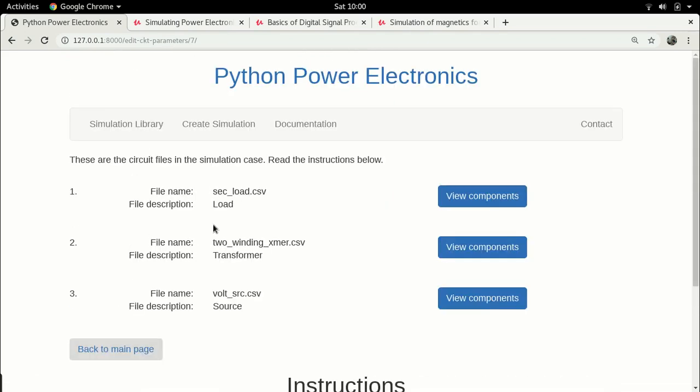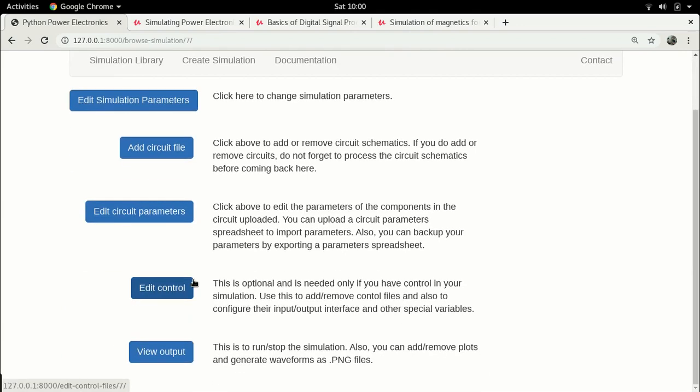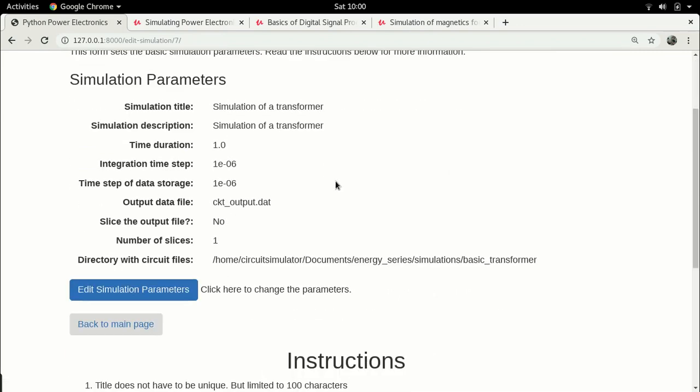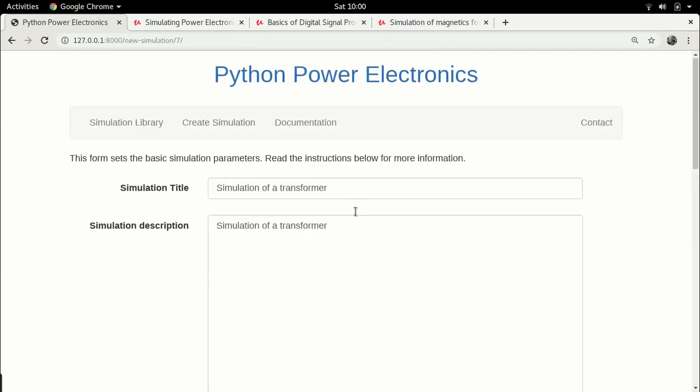So since we have a frequency that is now almost, you could say, 200 times what it was before, you would say that in order to be able to simulate this new system, which is 200 times faster, your integration time step would be necessarily 200 times smaller, right? So therefore, what I would do is I would decrease this integration time step by an equivalent amount.